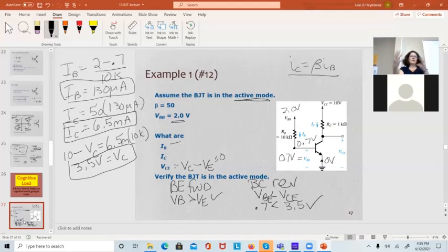And then you go check the pins on the transistor and make sure that they're actually the right ones. It's a three-legged device. If it's late at night, looking at that picture on the data sheet, I'm sitting there holding the transistor and I'm putting it in exactly the same orientation as the picture, make sure the flat side is facing the same flat side, and then I look at it and I go, okay, base collector.